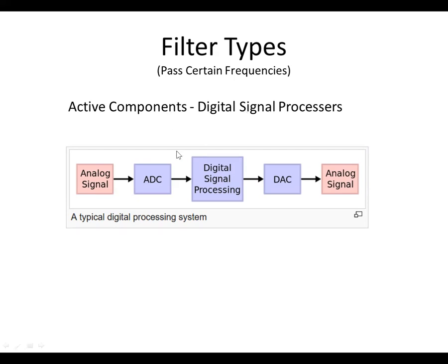digital signal processor. And this is something that's been around for a while. I mean, it's been around so long, I actually studied this in school over 40 years ago. What's changed has been the technology, the components, and the system architecture to do these kind of things. But basically what a digital signal processor does in terms of filtering is you take the analog signal that's coming from, say, the receiver, and you've got it into the IF stage, and you want to filter it.